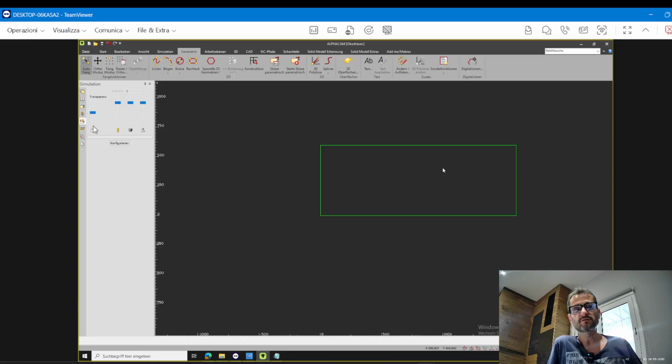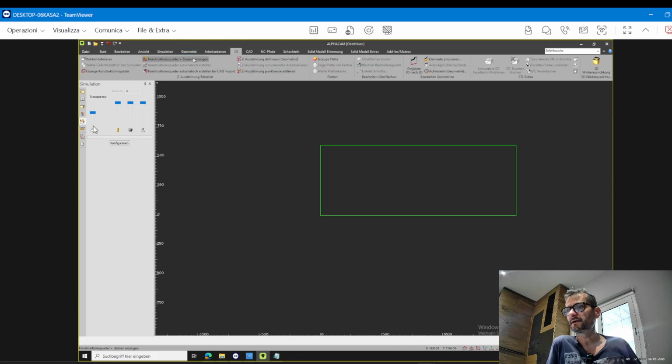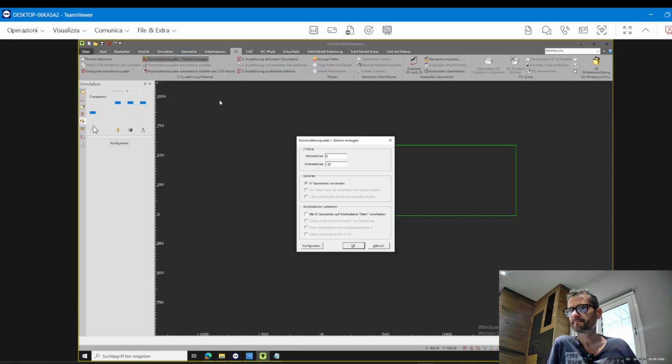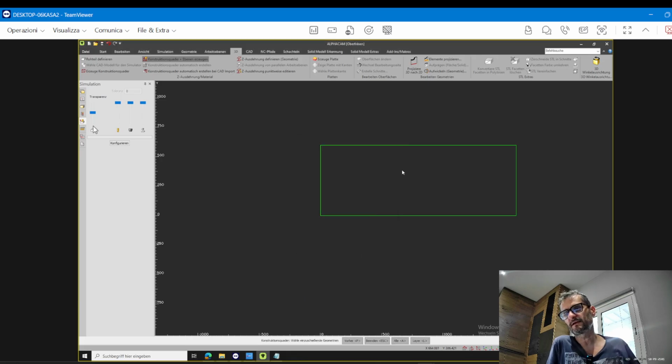Now, if you want to create the 3D, you can do it by the menu 3D. You have a menu, it's called 3D. And this one, yes, right. For example, -20, it's okay. And you just say okay, and you pick the square after. You say okay here, and just you go near to the square, to the rectangular, sorry.